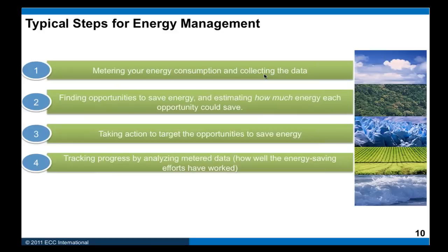Here is an easy way to show what are the typical steps if you were to follow energy management in your organization. Very quick, we will look at it from an ISO perspective in another minute or two, but here are the simple set of steps, guys. Number one, you need to know what is your energy consumption right now. Like they say, what you cannot measure, you cannot manage. What you cannot manage, you certainly cannot improve. So meter your energy consumption and collect as much data as possible of the current status.